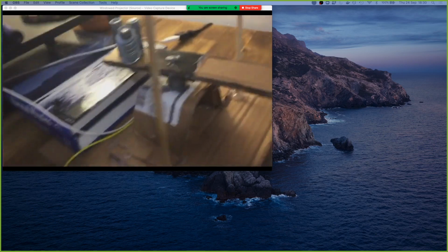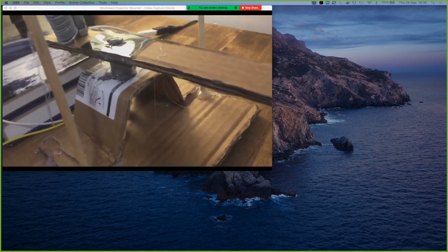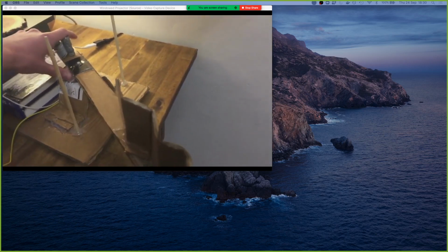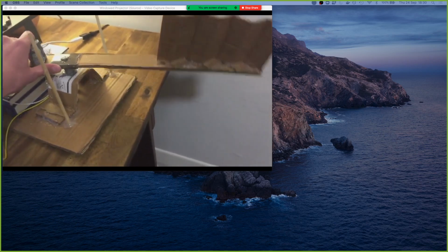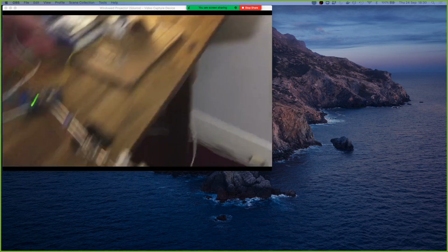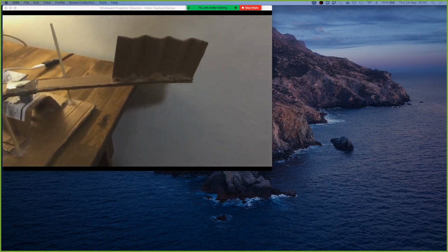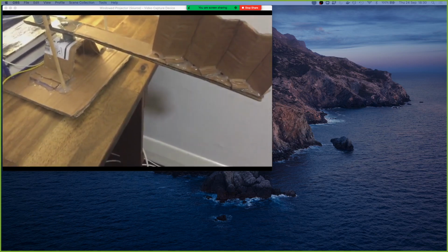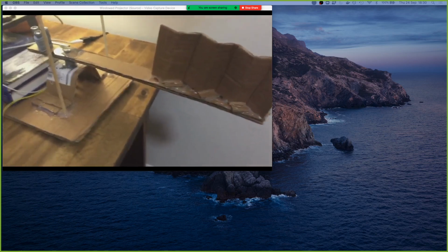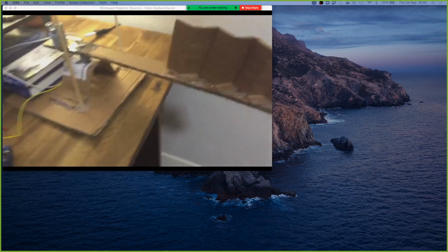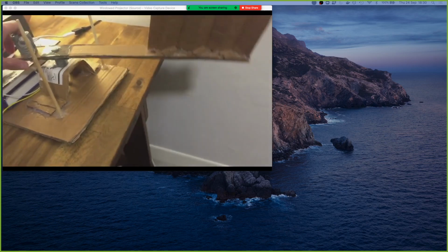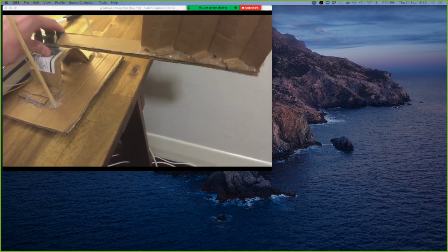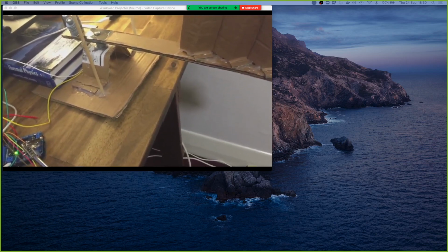And the input is going to be the control signal to the motor. So the motor obviously turns this left and right, or clockwise, counterclockwise, right? By virtue of the motor turning, the distance between the sensor and the paddle, I'll call it a paddle, is going to change. So maybe not a completely useful physical system, but it's going to implement the idea of a feedback loop, a control signal, and we can see how the motor is going to act in response to the reference signal and deviations from the reference signal. And we'll talk about some practical things that have to do with that.